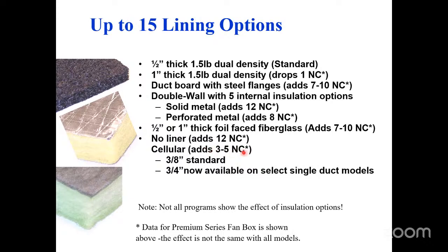So pretty much there's only two real choices, in my opinion. You either get the low cost, cheap, entry level, 1/2 inch thick insulation, which is the best for sound, and roll with it. Or you tell me you need cleanability, you need to wipe this thing down because it's a special laboratory job. Then you should get the cellular foam insulation and have a minor sound penalty. Don't pick anything else. Everything else is stupid. We have all of these. Every manufacturer we deal with offers every one of these things, and you could buy them because some people ask for them. But those are the only two you should even think about.